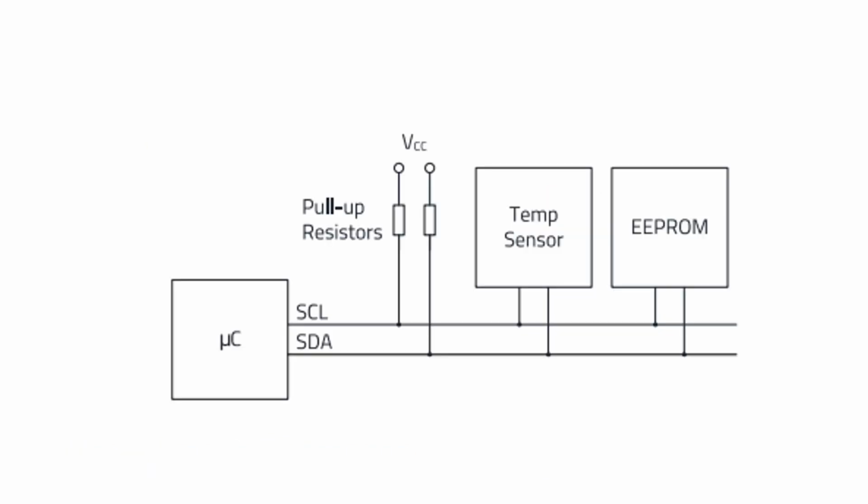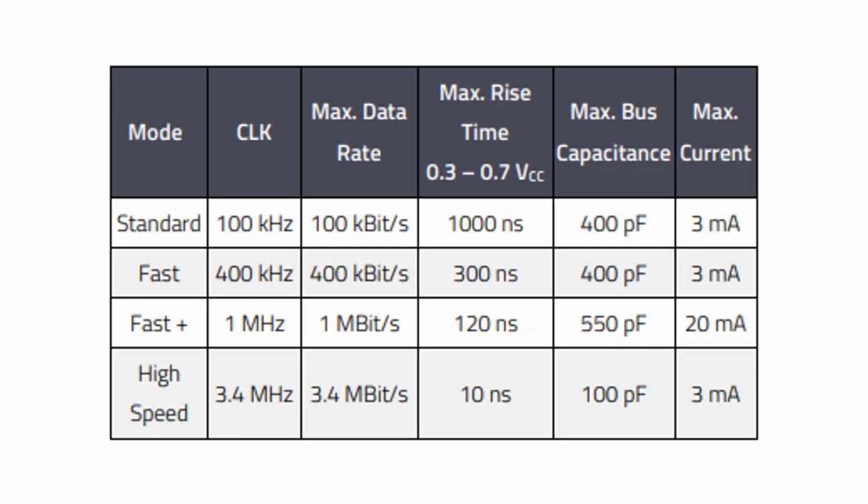The I²C operates according to the master-slave principle, whereby the master always initiates the data transfer. Due to its low complexity, the bus has achieved a wide distribution. However, the protocol is very simple, and the physical topology is only single-ended. So in practice, both of these factors mean that the bus can be very susceptible to external interference, especially during EMC tests. This table shows an overview of I²C specifications.